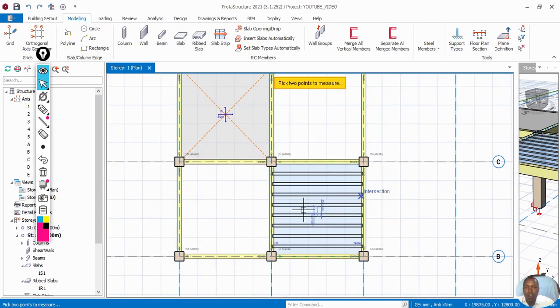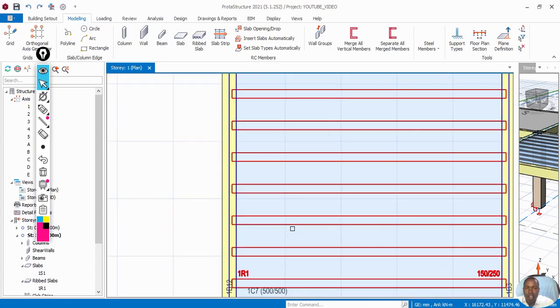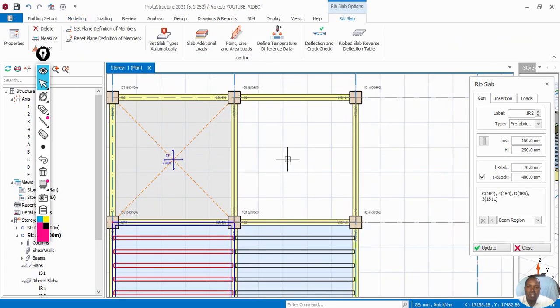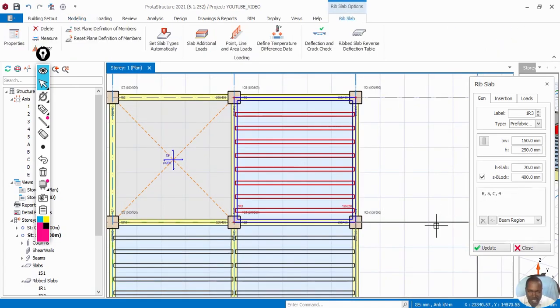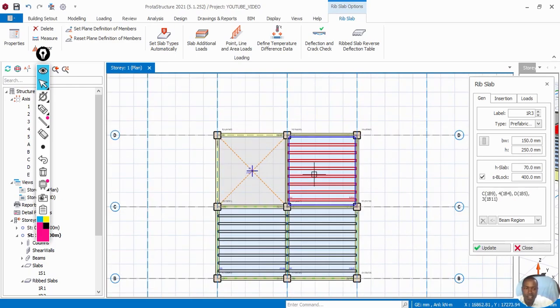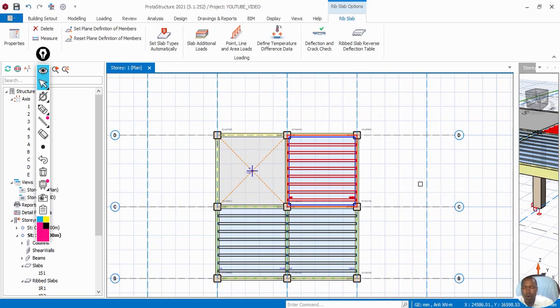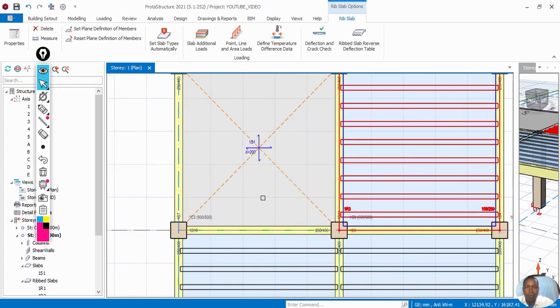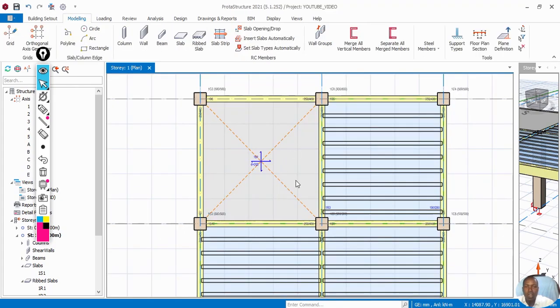Yeah. So if I press escape, come back, double click on this one, I can press it in also this one, press it in also this one, as we did in the slabs. Then after that, I told you we would draw line loads on the top of the slabs. In most cases, on the ribbed slab, we don't put line loads or wall loads, but we usually put them on the solid slabs. How shall we do it?